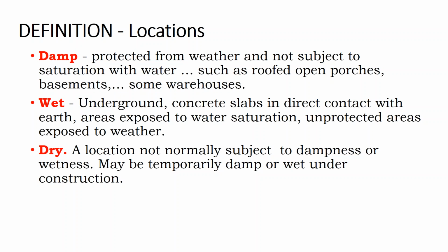And so you are buying solar cable for up on the rooftop, and maybe you buy a big spool, and you get to the point where you're ready to go into the building with your cable run, and you say, well, can I just take my solar cable that is rated for the hottest part of the rooftop for a wet location? You would think that you could just run it in conduit down to your electric service panel. That's a dry location. If it's good for a wet location, certainly it's good for a dry location, right? Well, it all comes back to maybe, maybe not. It has to be cross-listed for that dry location.